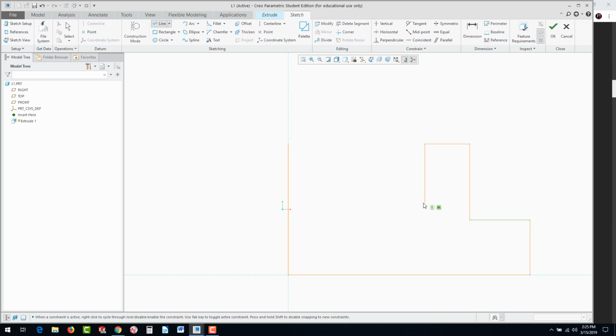Again, if you watch the first minute of this E1 video or go back, you'll see you could search through there and find it. I'd like to have the automatic constraint of equal come up because it's very useful. But I don't want it here. So move it to where there's no equal symbol. Just the vertical line, click, drag this across, stay away from equal symbols, click, drag it up, and infer.